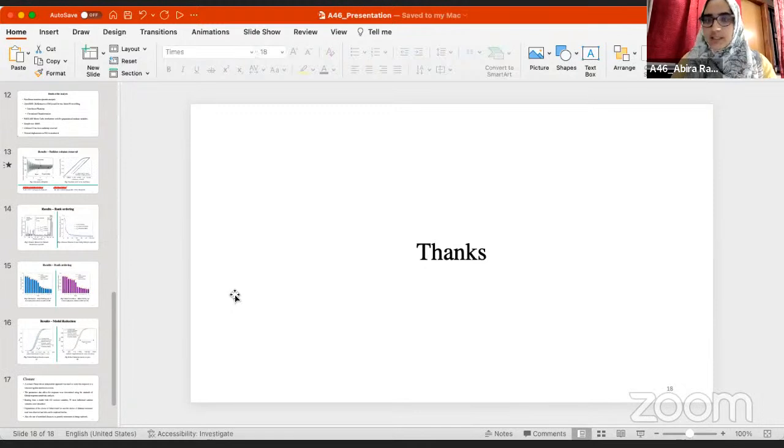Okay, so I'm not considering damping directly as a random variable, but the way my software works is that I'm using Rayleigh damping, 5% stiffness proportional damping, and it's calculating that damping based on the material properties, like all the properties of the frame itself. So in some way, yes, the randomness in the damping is being considered, but I'm not providing a probabilistic model for damping. Due to the randomness in the material properties and randomness in the loads, it is implicitly being taken into consideration. But I'm not modeling damping as.